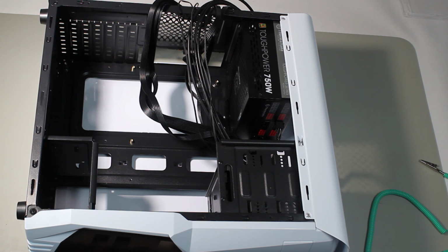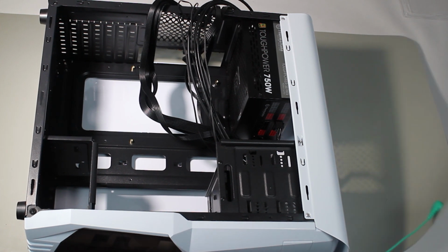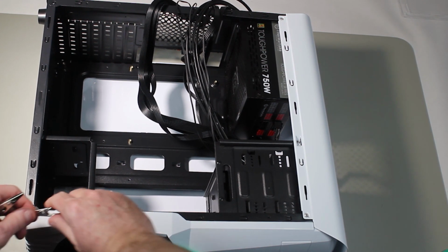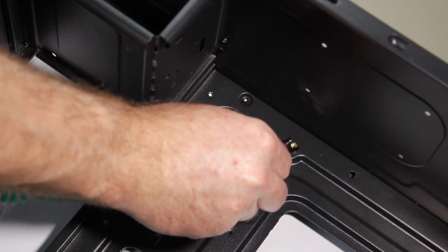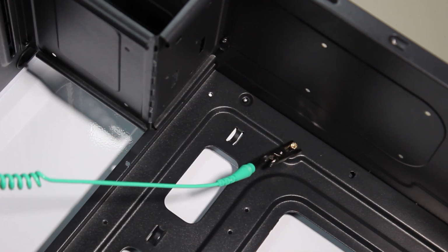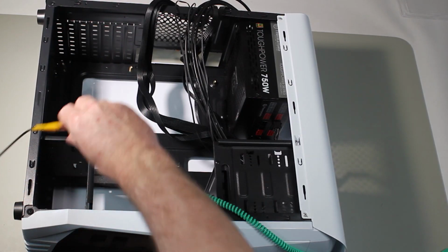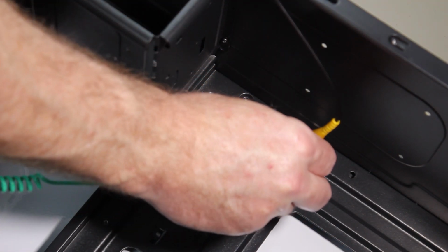More on that later in the video. This computer case has some standoffs pre-installed, so I will use one of the standoffs for the anti-static strap. I know I can use this standoff as it is only used with larger motherboards, and the motherboard I am using is a smaller motherboard. So I will attach my anti-static mat to the standoff. Next, I will attach my anti-static strap to the standoff.